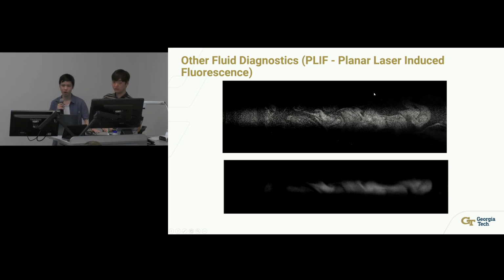I think it's more of a situation with the laser and how the light is reflected in that area. It's not necessarily that there is no fluid going on up there. When we're talking about PIV, which is particle image velocimetry, we have a high-powered laser to reflect off of the particles at a certain area, and when it comes to that sort of precision, for example position, the particles in the center are more in focus, reflecting more light back into the lens of the optics in the center.